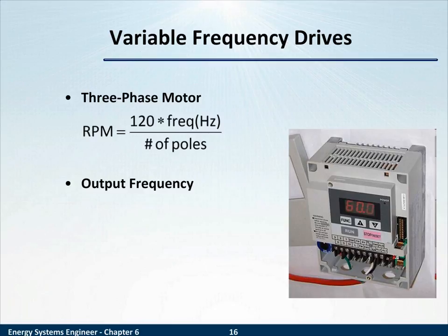Now this long definition is worth your time and attention to understand, the specification definition of a variable frequency drive. A variable frequency drive changes the speed of a standard AC induction motor by changing the voltage and frequency of the electricity supplied to the motor. Remember, the motor responds to what it's given.